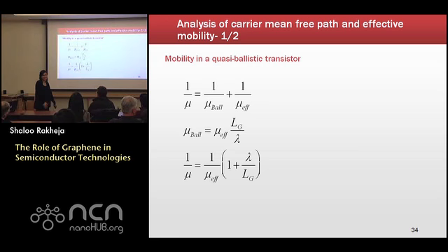That's a very good question again. Right now, the output resistances are very, very low for these devices, and these are very contact limited devices. So we extract the VXO from the devices and we hope that it is what we are really expecting it to be. That's a very open-ended question, and I don't have a good answer. You don't get any output impedance here. So we don't know if we can use it for logic or for those applications.